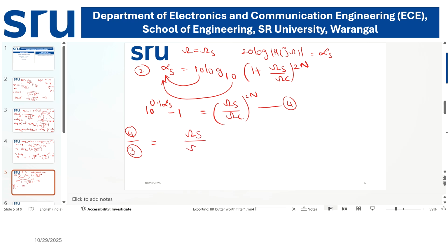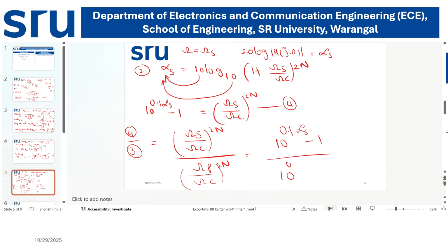(omega s by omega c) whole power 2n divided by (omega p by omega c) whole power 2n is equal to 10 power 0.1 alpha s minus 1 divided by 10 power 0.1 alpha p minus 1. Now here omega c and omega c can cancel.